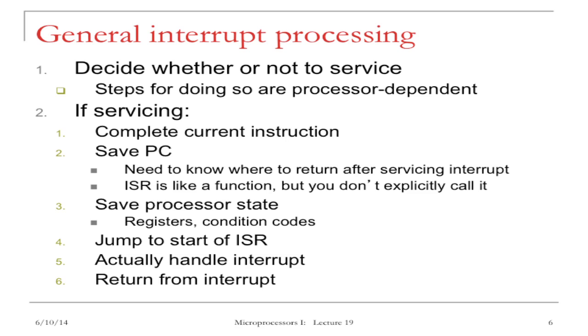The operation could be to acknowledge the interrupt, or to transfer necessary data between the microprocessor's memory and the peripheral device. At the end, the interrupt service routine will return. Because we saved the program counter at the beginning, that's why we can get back to the main program once this ISR is completed.